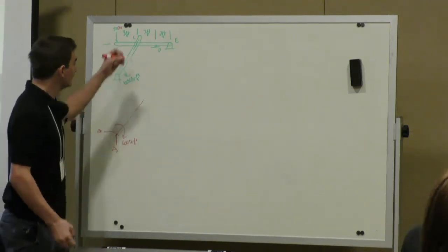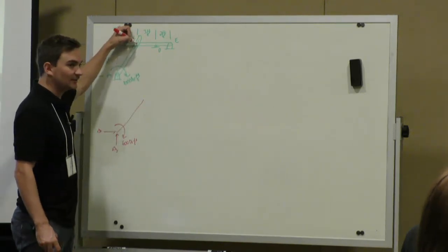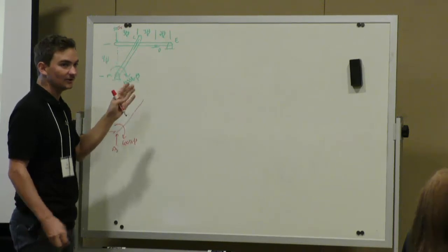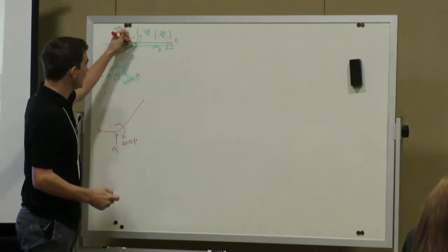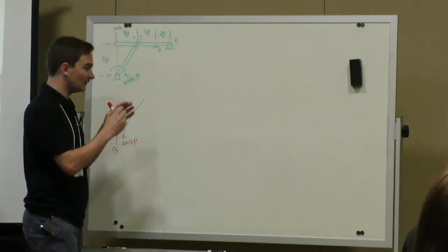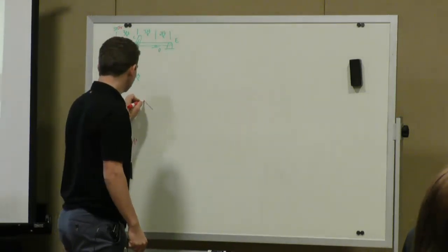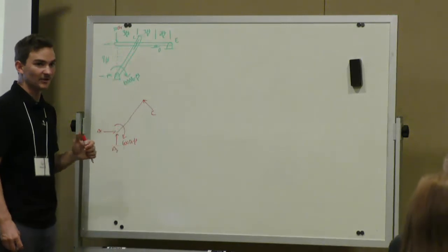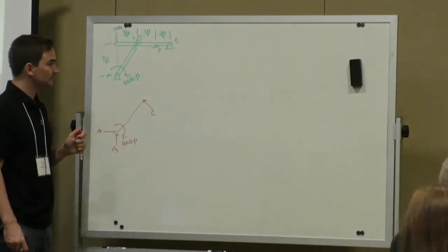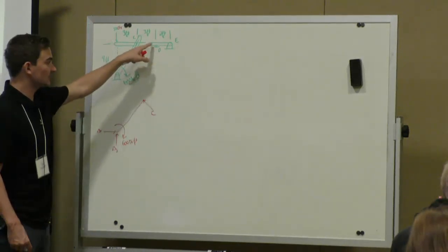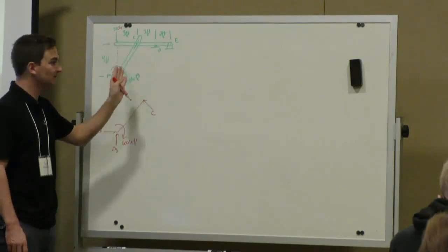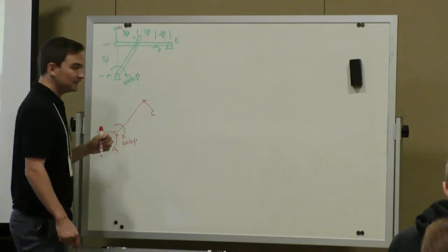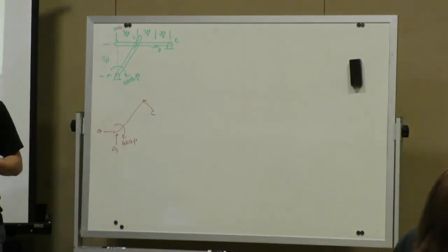Very good. Yeah, so our reaction at C, the key point to see here is our reaction is going to be perpendicular to the bar. So since that force of this pin is being exerted, we're just going to label it as C. It's going to be perpendicular to the bar. So similar with a roller, it acts perpendicular. So what angle is this going to act at now? Or what are the sides going to be?